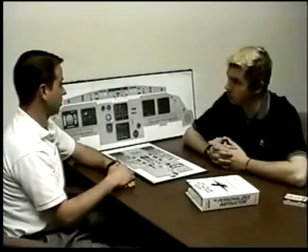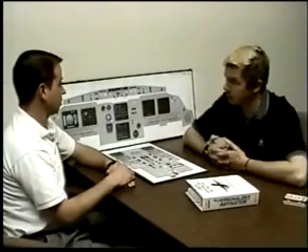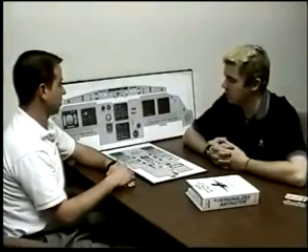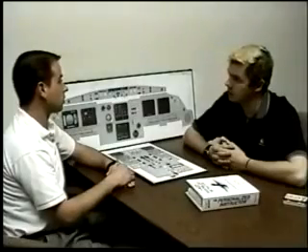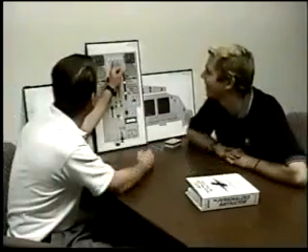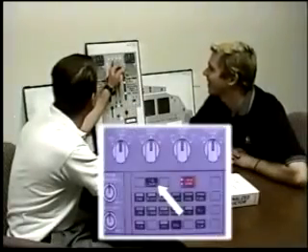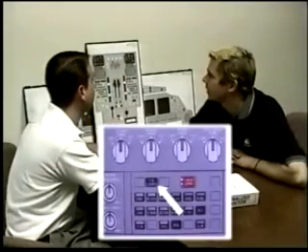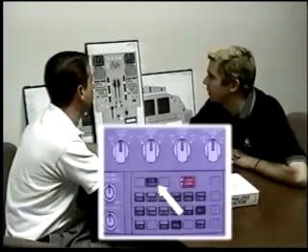Or in the event I have a dual altimeter failure, it can't tell what altitude I'm at, so anytime I don't have the gear down and the flaps are at full. On the ECAM panel, we have a takeoff config. What are you doing when selecting the takeoff config? I'm simulating that the thrust levers are applying takeoff power in order to test that all the configuration parameters are met. What are some of those configuration parameters that are checked?